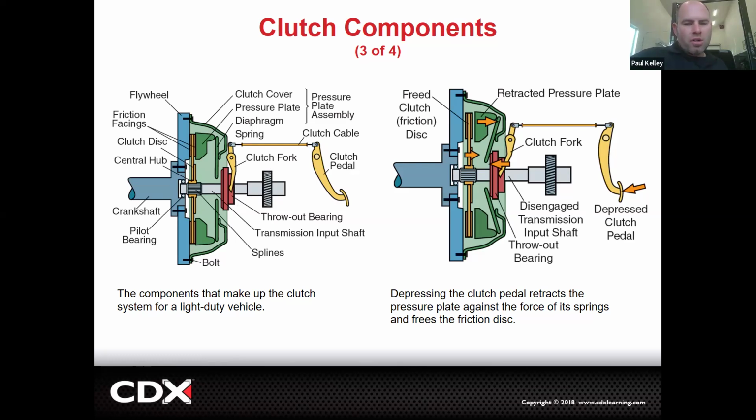So you got to center it first, and then you're going to actually torque that pressure plate. And then the input shaft of the transmission should go right straight in. You might have to turn a little bit, but it'll go right in there. So that's why we do the alignment tool. This is just a good view of that. And then, like I said, the clutch disc is in there floating, except it's squeezed, but technically there's nothing holding it there, then we would put that clutch cover, and that's why they call it the cover.